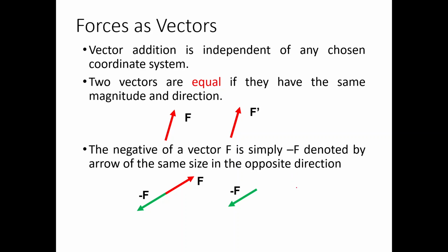Usually in civil engineering, what we term our forces is: if we go up, that's a positive force. When we go down, that's negative. When we go right, that's positive. When we go left, that's negative. Then for the torque or the moment, if we have clockwise, that's positive. If we have counterclockwise, that's negative. So that's how we term our forces in engineering.